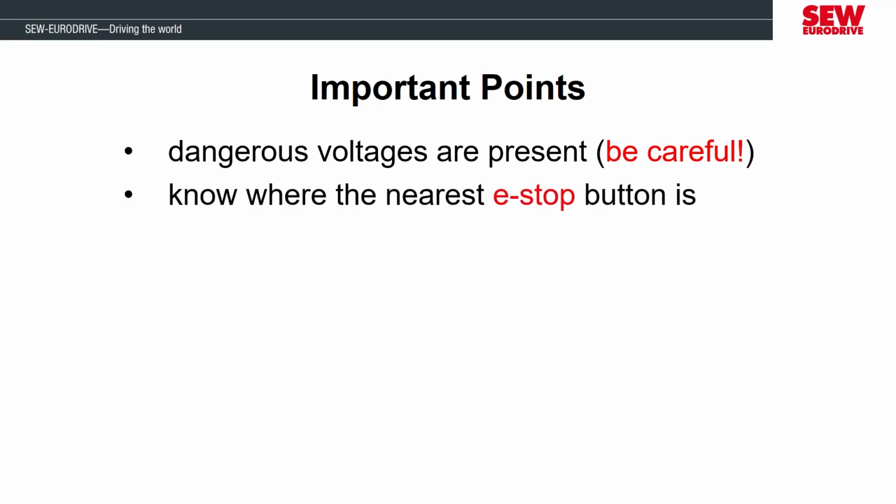We will be changing inverter parameters throughout these activities, and in a training course with constant parameter changes, it's possible that the motor or inverter could make scary noises or have unexpected behavior. If you lose control of your MOVIDRIVE or motor, you should have some way to switch off the power supply voltage immediately to the inverter. You should know where the nearest e-stop or disconnect switch is, and it should be quickly accessible.